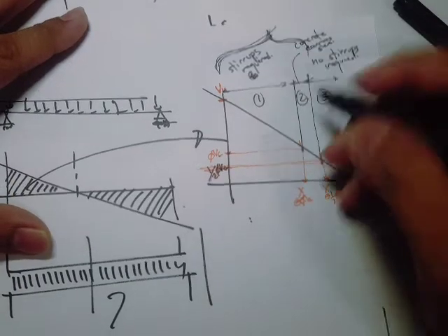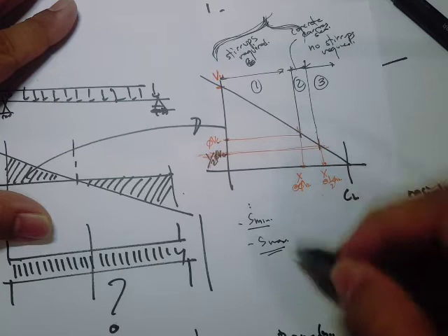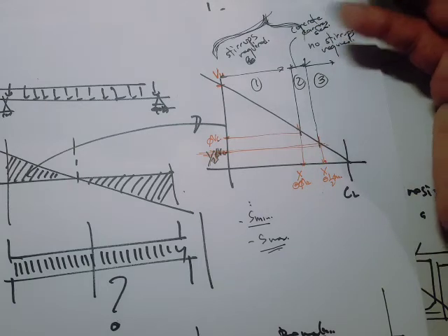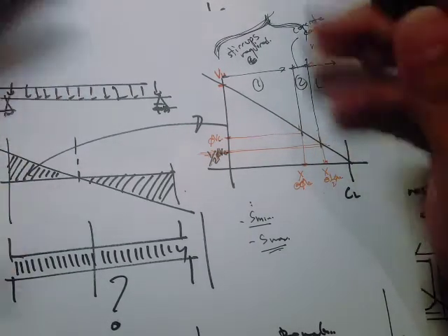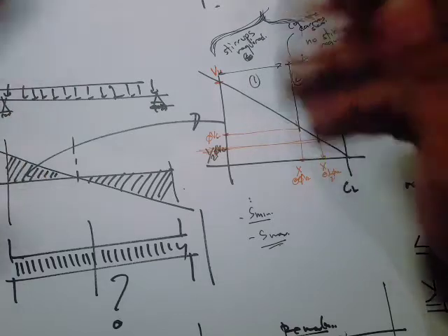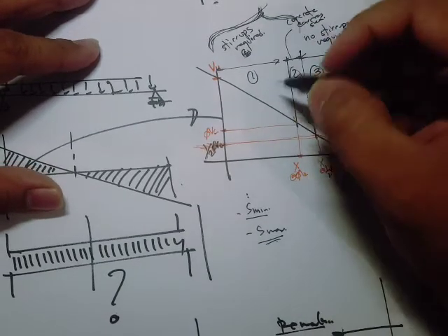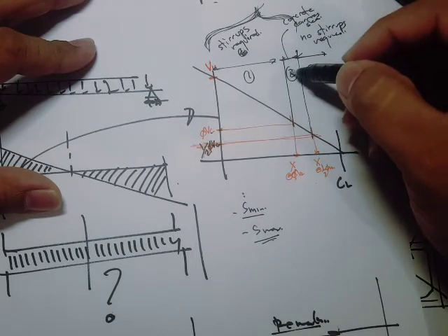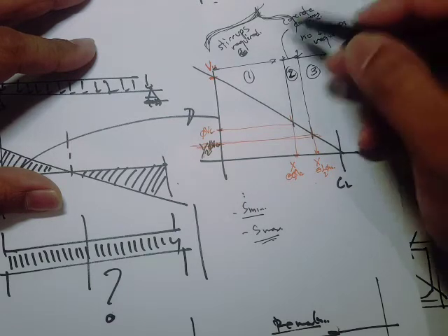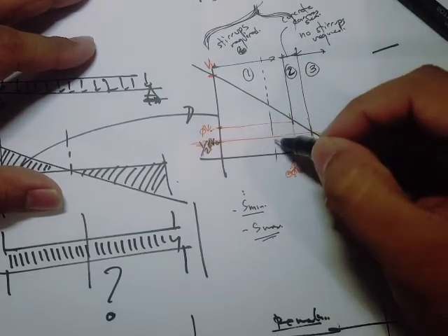Okay, so there's going to be a minimum spacing as well as a maximum spacing. The design of this stirrup layout, or stirrup spacings, is to determine up to where the minimum spacings would be, and then where the maximum spacings will start. Even though here in section 2 it is obvious that we can utilize the maximum spacing, at some portions it will actually start somewhere here.